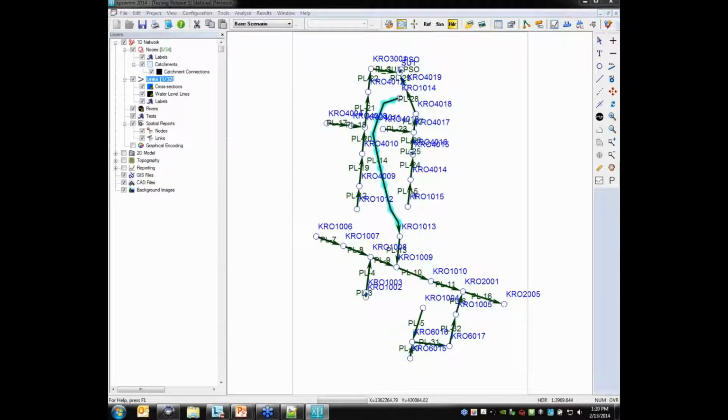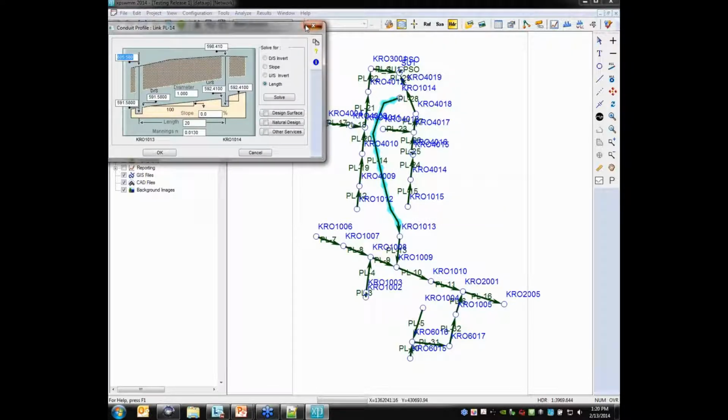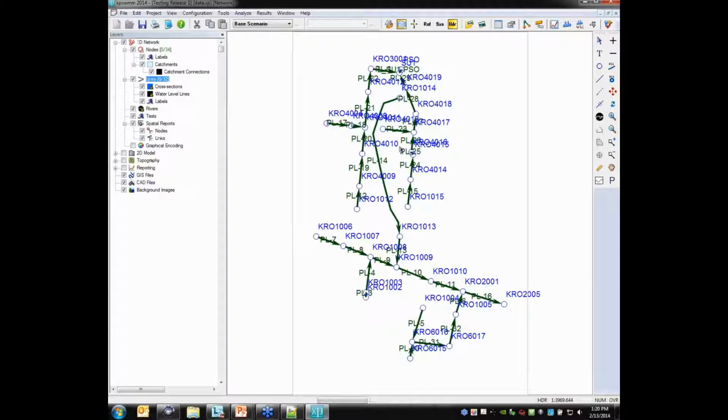So that's a nice way, especially since typically speaking, the geometry, or the way that the file itself looks, doesn't change as often as the input data, and certainly doesn't change as often as the output data. So it may be a very valid workflow to use a shapefile or some other type of intermediate GIS file for geometry, and then use something like a database file for the data. It's really not a bad way to do things.